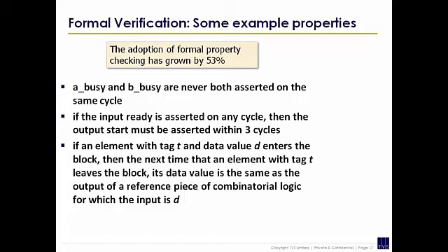And ARM just recognizes there's no way they can find all their bugs with simulation anymore, because there are too many corner cases. They can't hit all the corner cases. They can't even identify all the corner cases, let alone try to hit them. So normally they put the corner cases into a functional coverage model, and then they've got their 2 buildings running 1,000 simulations, and they try to hit the coverage model. But they realise now that's virtually impossible. So they start to use formal verification as well.